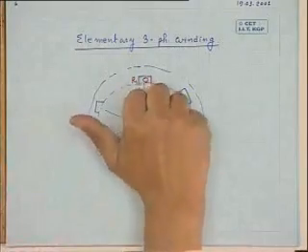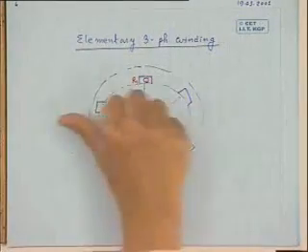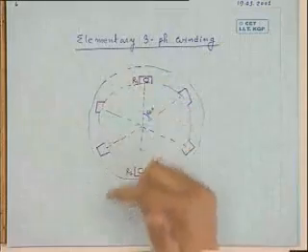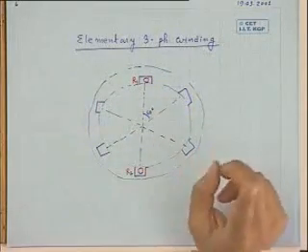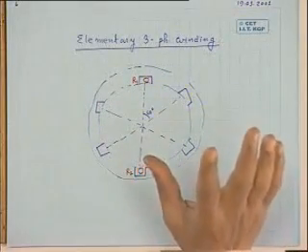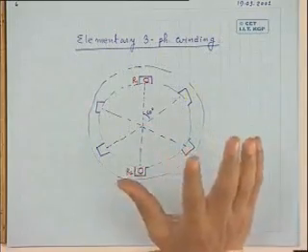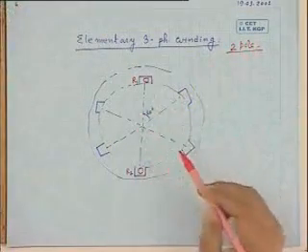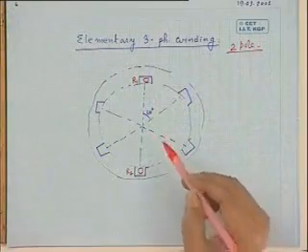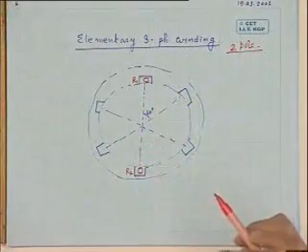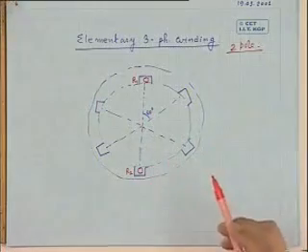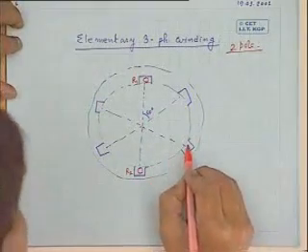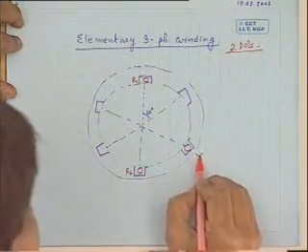Because whenever any phase carries current, it will produce only 2 poles, north and south, like this. How many poles an individual coil can produce will decide the number of poles of the machine, as we will see later. But it is certainly a 2-pole configuration, because I have put the return coil side in diametrically opposite slots. So R1, R2.